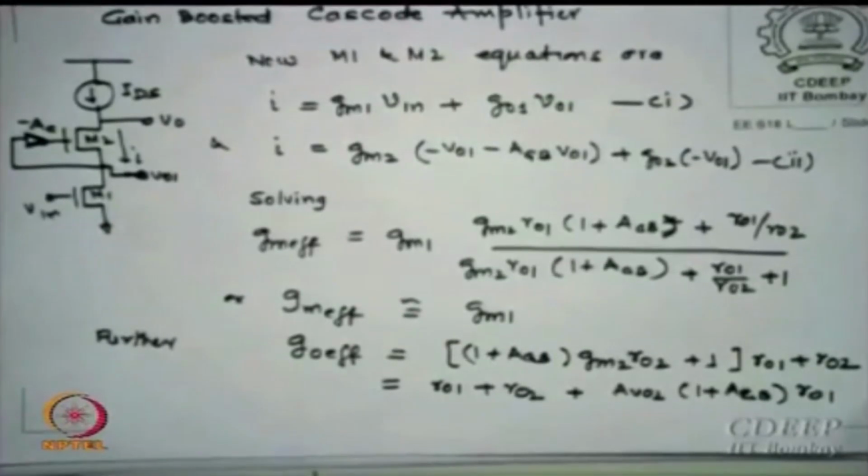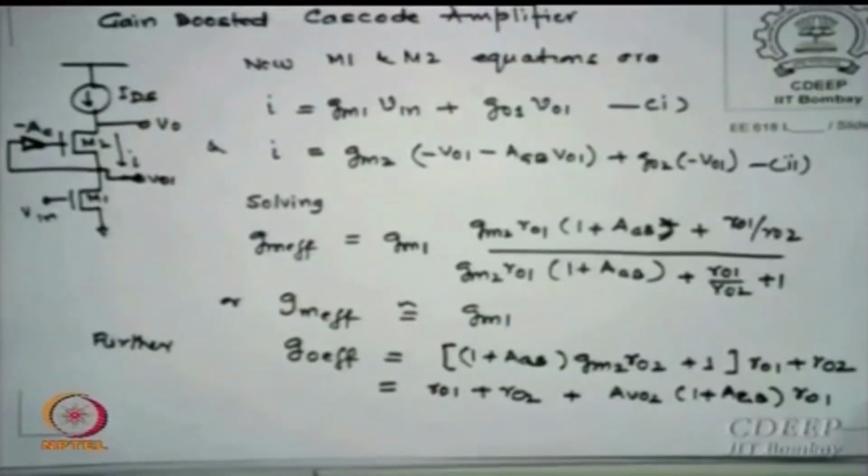Now already you have boosted the gain. Now I have an amplifier which further boosts the gain. What it should not change, again being a Cascode stage, is the GM, but what should change is that it increases RO effective. So you want an even better current source now, another case in which I can have a gain boosted Cascode amplifier. Okay, the method here is simple.